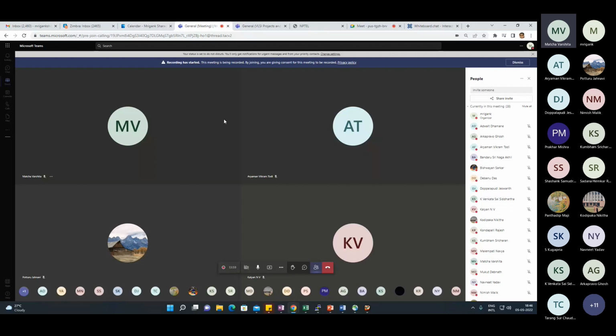In the noise analysis part, in the small signal model, we are dealing with the power of the noise, like power of the signals. But can we apply KCL, like in the small signal circuit where we applied KCL and found the input referred noise and Von? Can we do that? Ultimately, you're looking at the Vn square, right?